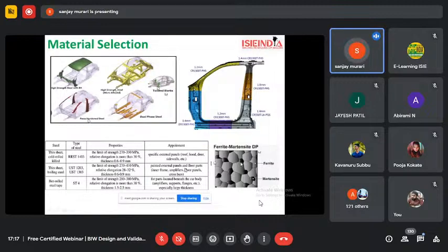From the austenite, if we go for sudden cooling, then the martensite will form and a few ferrite structures will be there in it. If we go for slow cooling, then pearlite, bainite, some other forms of steel may form, which will have different properties. Martensite has very good strength because of its HCP form.